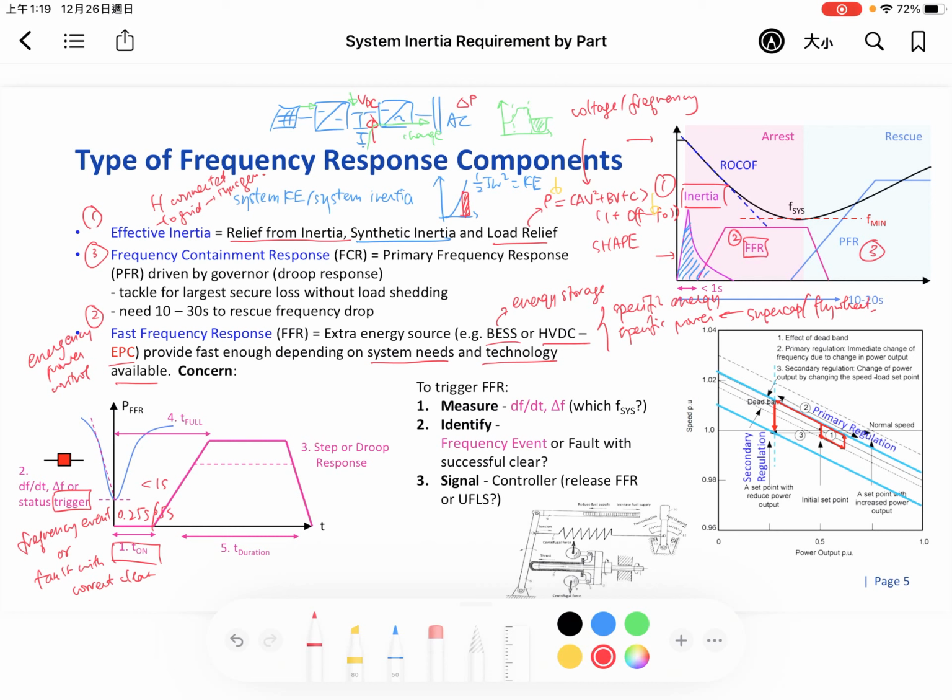Just like there is a cable fault, but we have enough transmission capacity, the system will have some frequency fluctuations, but the system can recover itself. You don't need to release. If you release so large, it's like you have a 100 megawatts capacitor or 100 megawatts battery, and you suddenly release it, then it will be a big problem because there is some power deficiency and it becomes over frequency.